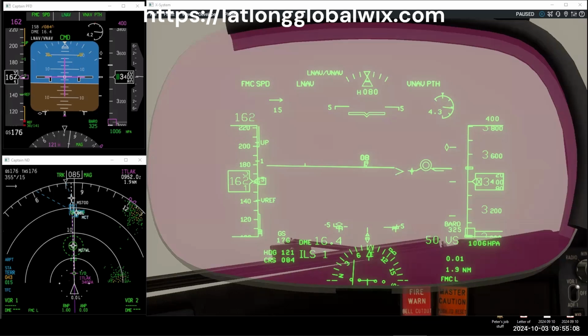We've gone back to the sim, and remember now this is a two-stage descent virtually from ITLAC 3,400 to Mike 07 Whiskey Lima at 2,200, but the final descent is Mike 07 Whiskey Lima at this particular airport. And we have drawn a 2 nautical mile ring around Mike 07 Whiskey Lima to remind us that when we get to 2 nautical miles prior, then we will configure gear down, flaps 15, speed brakes armed, and then configure to landing flap, in today's case, flap 30.